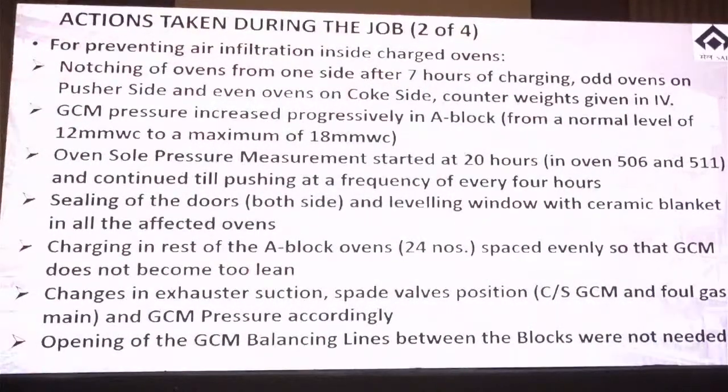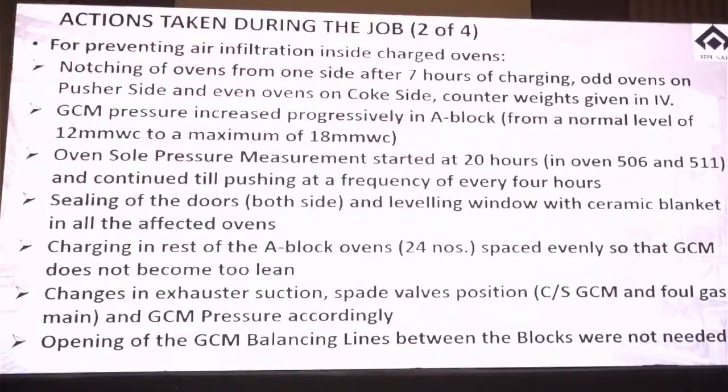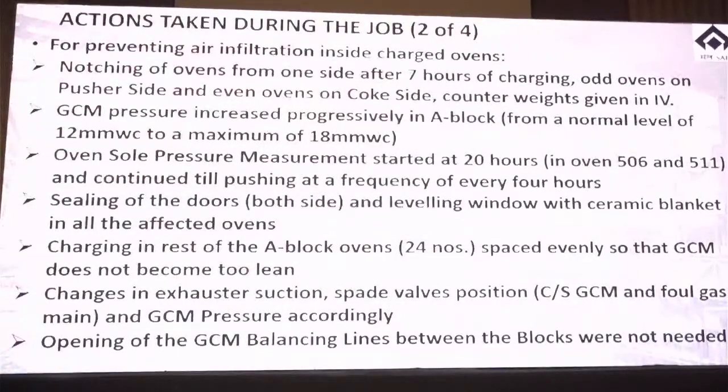Oven sole pressure measurement started at 20 hours in the ovens in which special doors were given, and it continued till pushing at a frequency of every 4 hours. Sealing of doors on both sides and leveling into a ceramic blanket was done in all the affected ovens. And we gave schedules in such a manner that the charging in the rest of the 24 ovens of A block was spaced evenly.